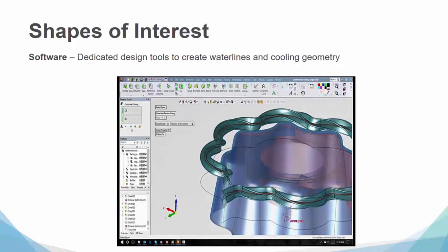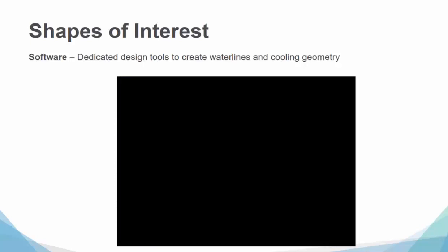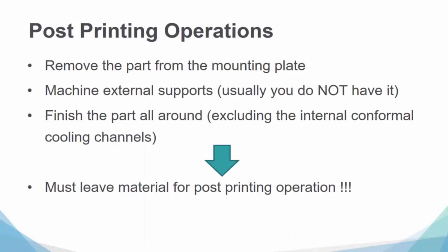Plus, there's a visual analysis that can allow you to check to make sure that that water line is staying a safe distance away from an ejector pin or a screw hole, or whatever the case may be. So it's checking as it goes.